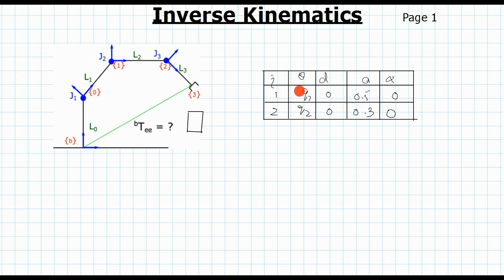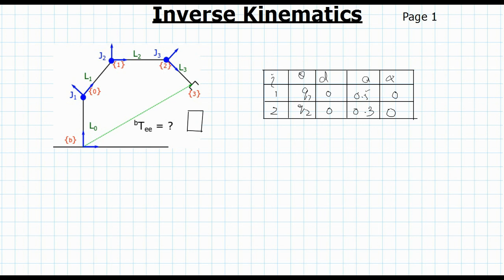So the DH parameters for the planar 2-link robot are given here. We have 2 links and 2 joints. This is evident by these entries. These are 2 joints and these are 2 links. And this is a pretty common way in which you will be seeing problems phrased in this class, that we are given the DH parameters. So first part would be that we have to sketch the robot. Then we have to do the forward kinematics and then compute inverse kinematics.